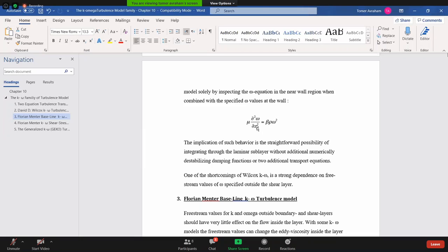You have to decide where to put the filter. But the difference is that in LES, we resolve some of the turbulence with the mesh, and we assume that the model for what we cannot resolve represents the dissipation down to the Kolmogorov scale.